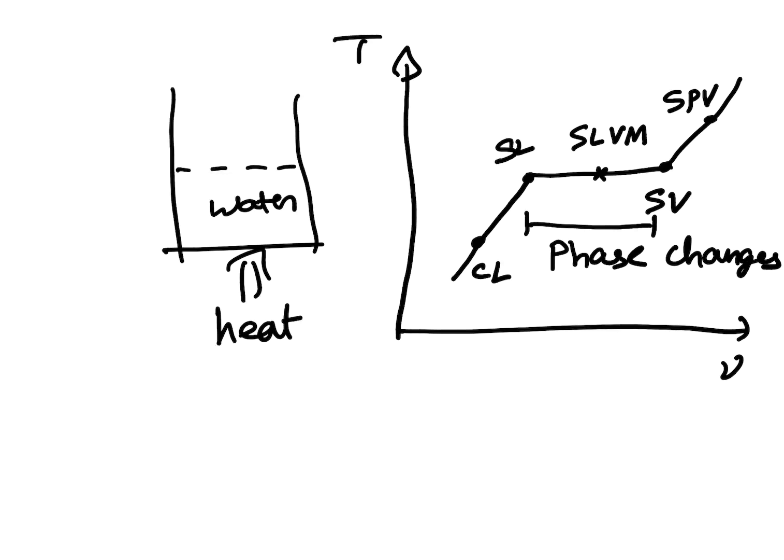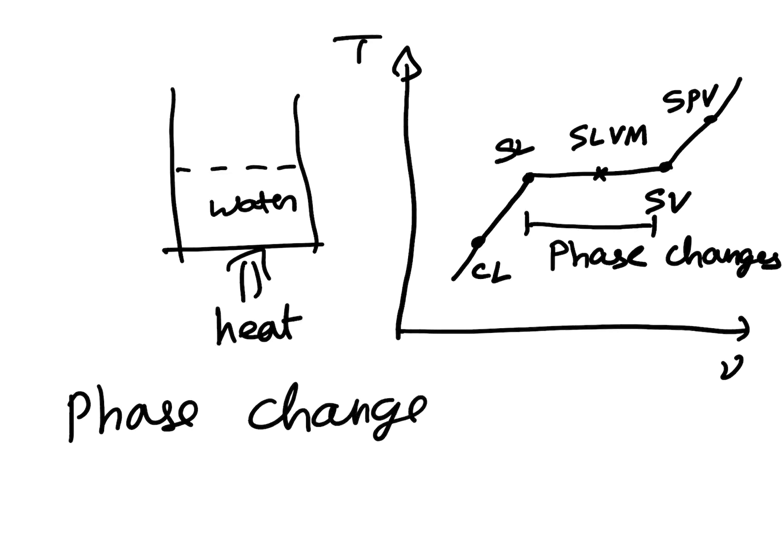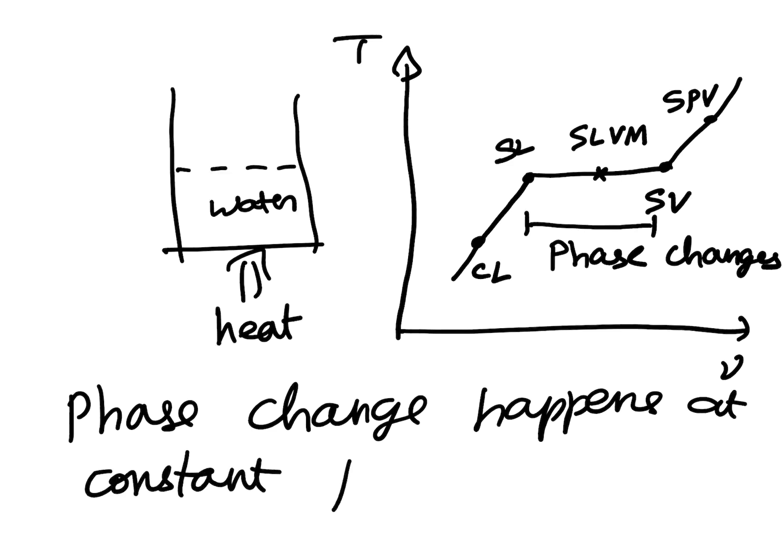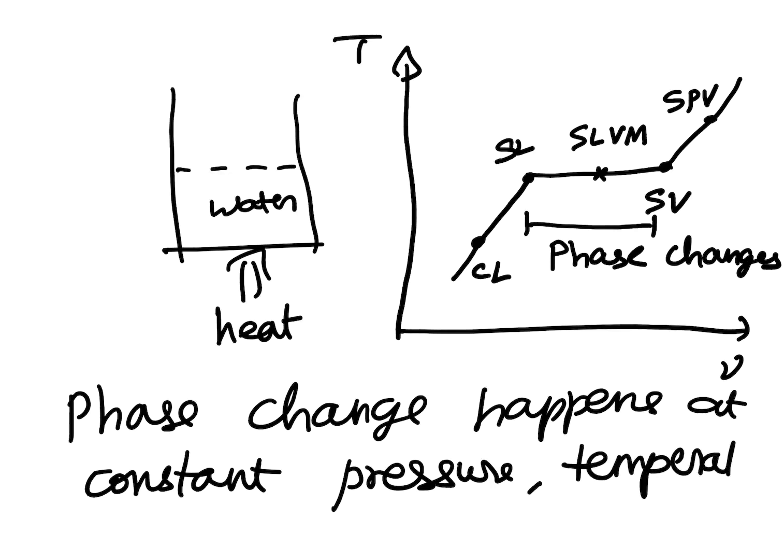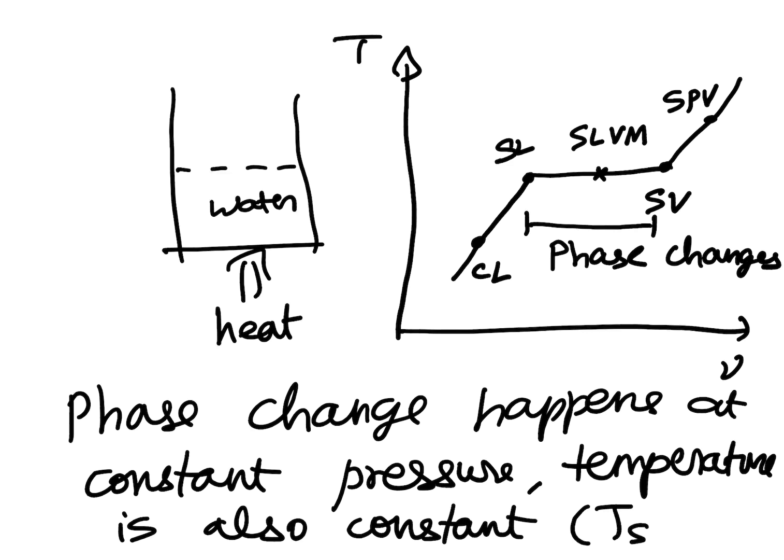Phase change happens at constant pressure, and until the phase change is complete, the temperature is also constant, and you know that it is equal to the saturation temperature, Tsat.